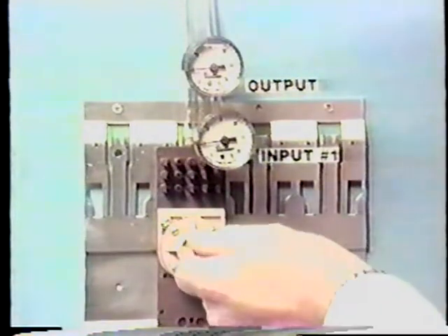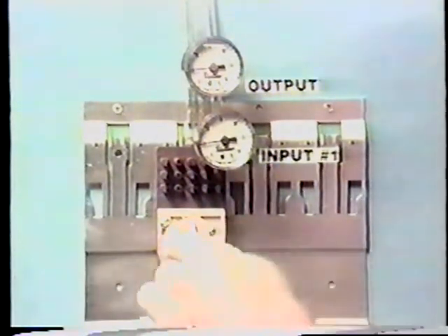This relay also has a bias adjustment, which can advance or retard the output signal if the application requires it. The summation relay can also be used as a biasing relay, if needed, by using only the input on S1 and adjusting the bias adjustment to advance or retard the output signal.